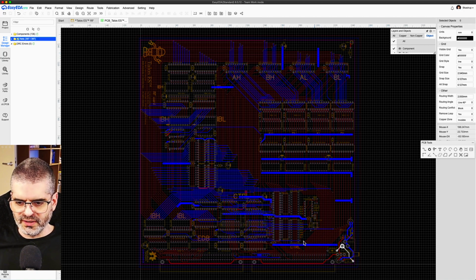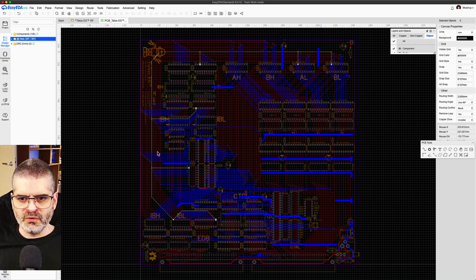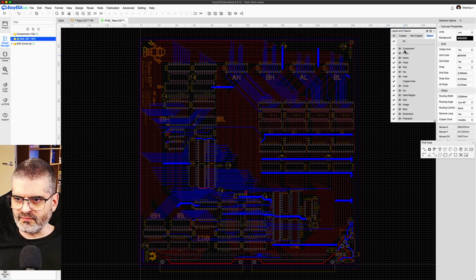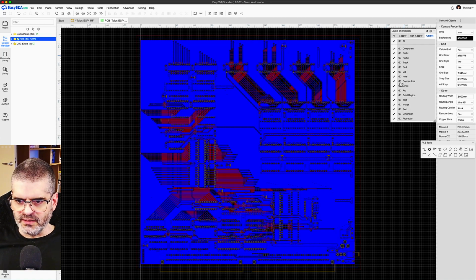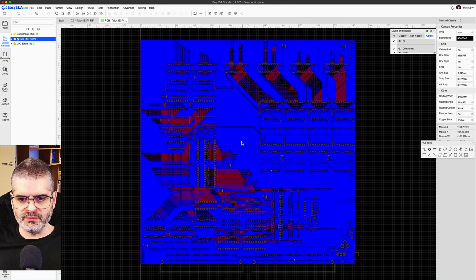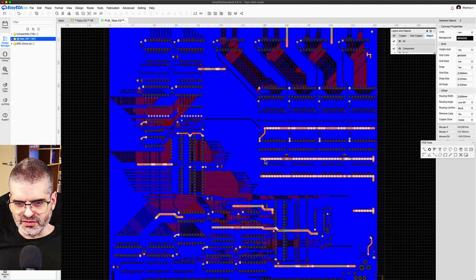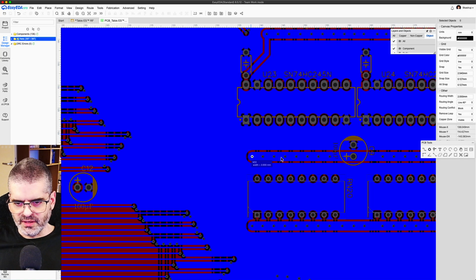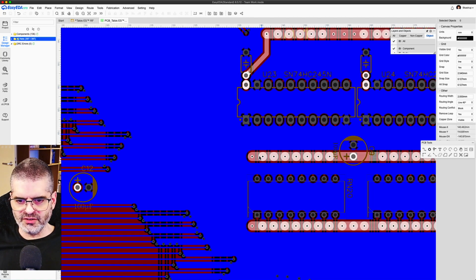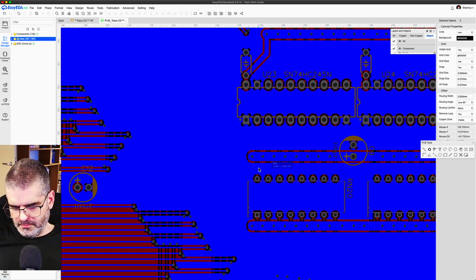It's to make sure that power goes from this pin everywhere, even when the copper fill has limitations. And if we show now the copper area, you see most of the blue here is ground, except these thick blue lines here with lots of vias, which are meant to stitch the copper islands on the top layer via the back. That's the idea.